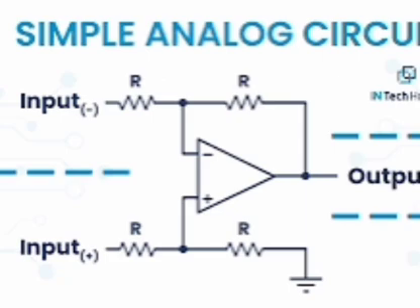VB dash E is V pi. RBB dash is the ohmic spreading resistance. CC means collector junction barrier capacitance. CE means diffusion capacitance between B dash and E. Typical pi model parameter values for a CE transistor: RBB dash is 100 ohms, R0 is 80 kilo ohms, C mu is 3 picofarads, GM is 50 millisiemens, R pi is 1 kilo ohm, R mu is 4 mega ohms, C pi is 100 picofarads.